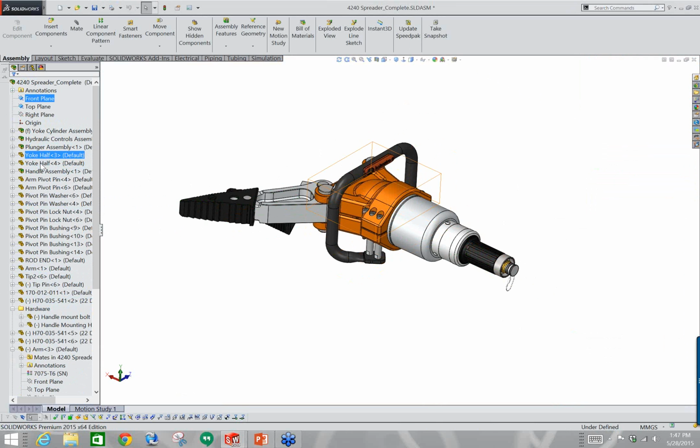Well, in this case right now, I've got 3 sub-assemblies, a couple of parts, and then another sub-assembly. Now, if I grab this sub-assembly right now and I try to drag them up in the tree, I get this, where it's trying to insert the sub-assembly into the other assembly, so it'll become a child of that sub-assembly. It's not really what I want. I really want to just drop it underneath here, right? And so it used to be we'd have to go in and drop it underneath another part, and then go and try to reorder stuff here and all that. It was always kind of a pain.